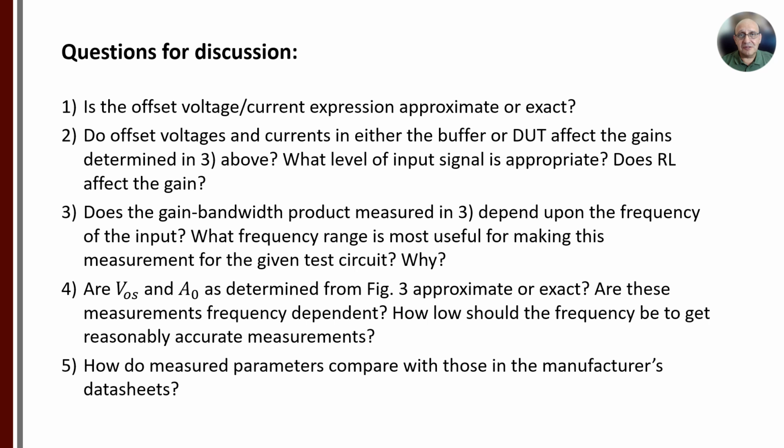Finally, we have some questions for discussion. Is the device's experimental data actually matching the theoretical one, or at least the manufacturer's datasheet? Now we are asking the questions about the measurement setup. In this case, does the load actually matter when we affect the gain? You would have to back up and redo the experiment, right, with and without the load. Does the gain bandwidth product depend on the frequency of the input? That's for you to answer once you complete the experiments.